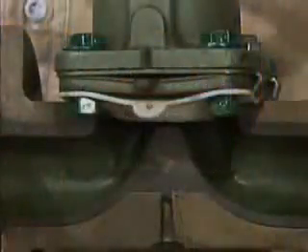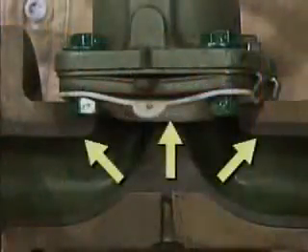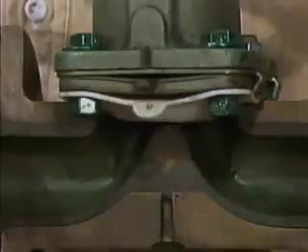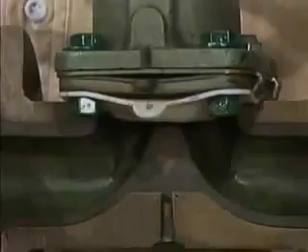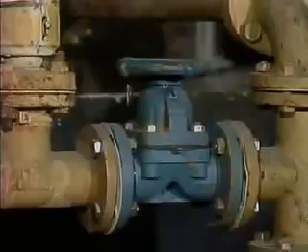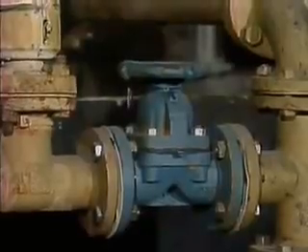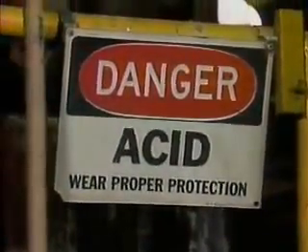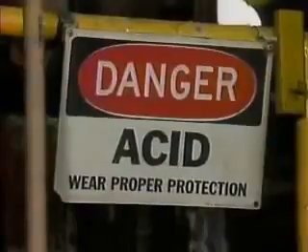In addition, some diaphragm valves have protective liners made of plastic or a similar material. The liners protect the diaphragm and the valve body from damaging fluids. In short, diaphragm valves are widely used throughout industrial facilities for a variety of applications, but they're particularly useful in systems that carry chemicals or hazardous gases.